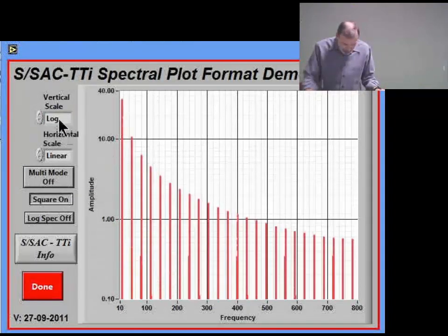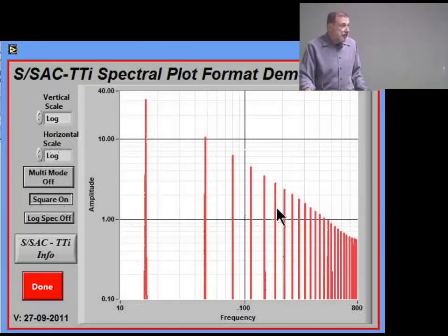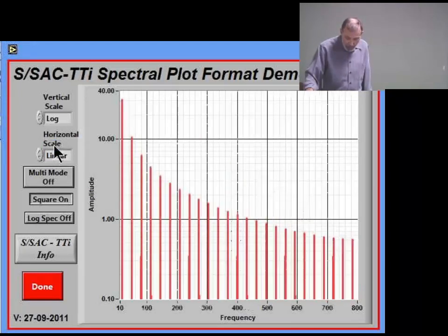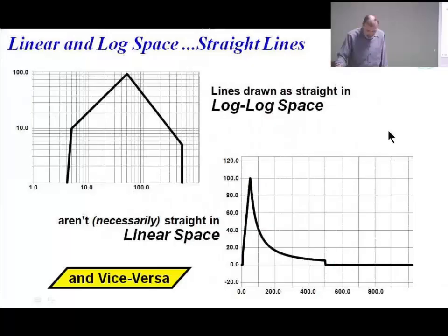We just said you should do it log to get the characteristic of the magnitude, but you want to do linear to show that all of these harmonics are equidistant apart. So if you're trying to show harmonics, then you want to use linear horizontal. All of these are examples of that.